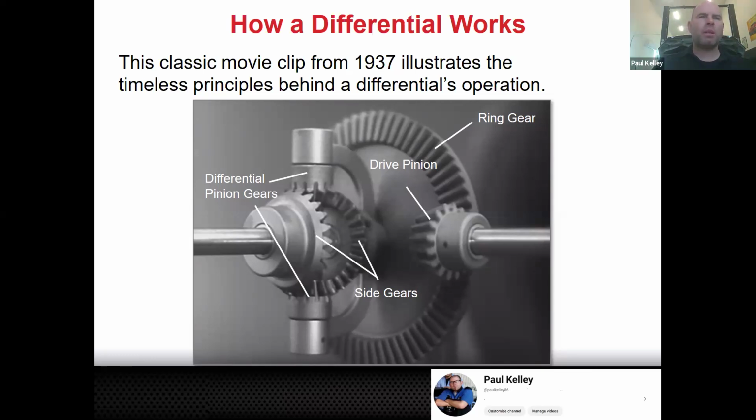Toyota doesn't call it the differential carrier because Toyota has a removable differential, and they call that removable part the carrier. Whereas most manufacturers use an entire housing, and then you actually have to put the differential in the housing. You can't pull it out and build it on the bench and put it in. So the terminology, I'm sorry, is very confusing. It just is. It's the way it is. But I'll get you familiar with all the different types, and then you'll know. If somebody says, oh yeah, I'm changing the carrier, the carrier could mean different things. The case could mean different things. What do you mean? Generally, the housing is the housing, though.